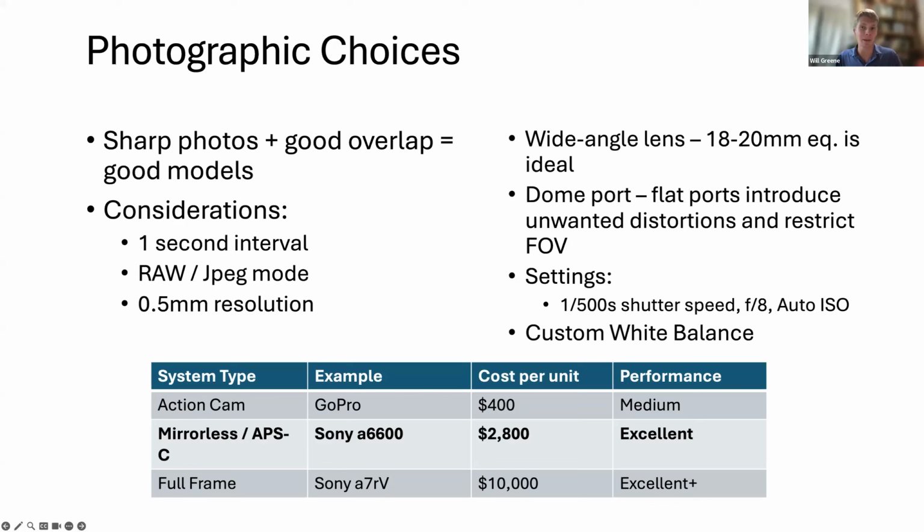The one thing that I did forget to mention is you need to be using Metashape Professional, not their basic. So the basic is much cheaper, and it does not include functionality that is critical to allowing ReefShape to be used, such as the ability to use Python scripts. You can't do that with the standard edition. So you have to use Metashape Professional 2.0 or above.